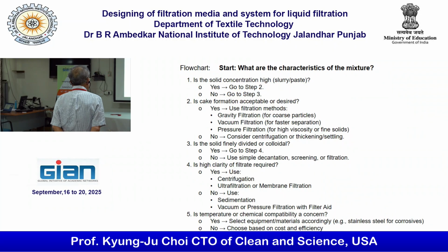Is cake formation acceptable or desired? Yes, use filtration method. Which one? Gravity filtration, vacuum filtration, or pressure filtration? If it is no, then consider centrifugation, thickening, etc.